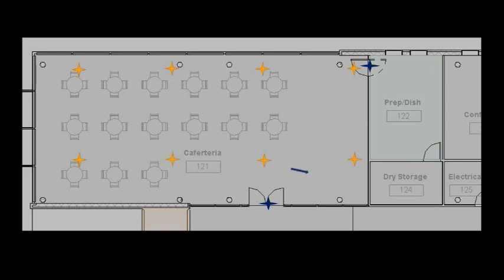From there, we'll find the wall that hosts that door, and we'll get a vector from there. So again, this is all about vectors, points, 3D calculus. From there, we'll do the cross product with the z vector and get these two normals from the wall. And then we'll move that point from the center of the room outwards, and now we have points all throughout the model looking like this.